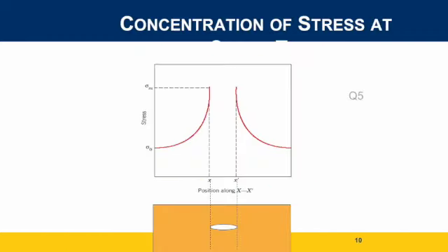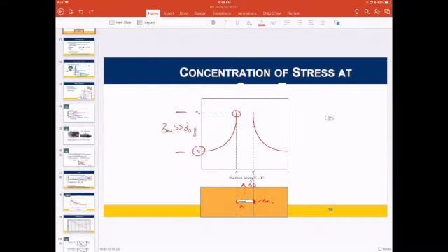All right, so this is just an example of how the localized stress gets higher as you get closer to the edge of a crack. And again, the edges are parallel to the stress, sigma naught, but the distance is perpendicular. Right? The distance of the crack is measured perpendicular, and then the radius of curvature is measured parallel to the stress. So this would be the sigma m. And as you see here, as you're further away, you reach sigma naught, but as you get closer to the edges of the crack, you can have a sigma m that is much, much greater than the sigma naught.